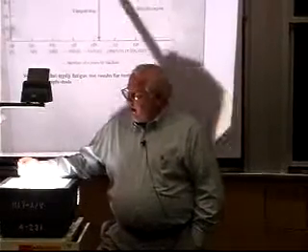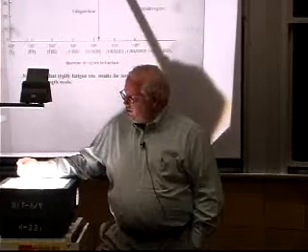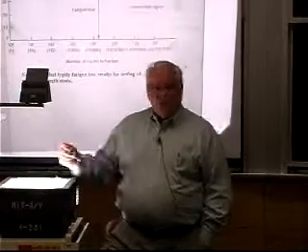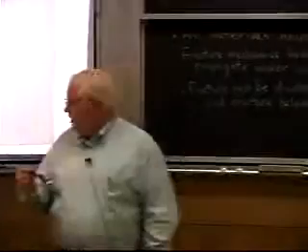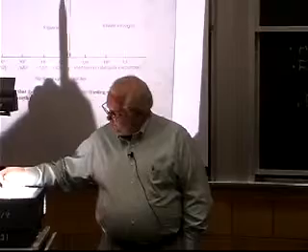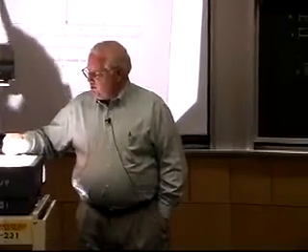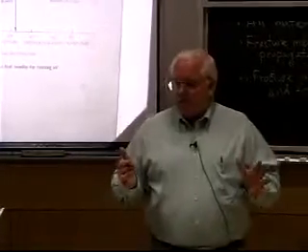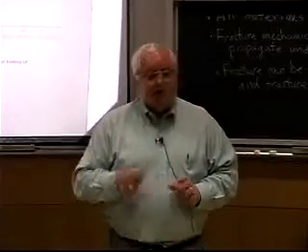Another thing that people have found, at least for steels, is there's something called a fatigue limit, and they define the fatigue limit as the stress below which you don't expect to find fatigue. We often talk about fatigue limits because steel has a fatigue limit. It's at around half of the yield stress, somewhere just below 50%, but depending on the strength of the steel, between 40 and 50%, you'll hit the fatigue limit. And if you design things properly, your material is essentially immune to fatigue below the fatigue limit, if it's steel.